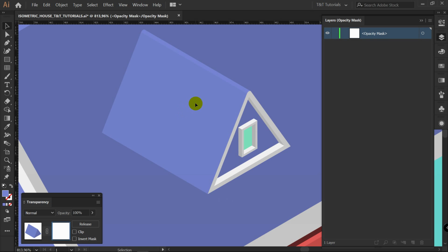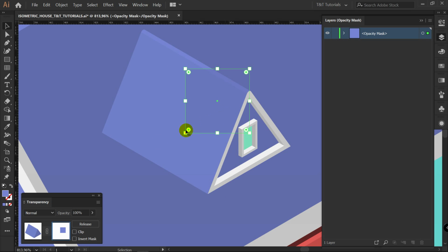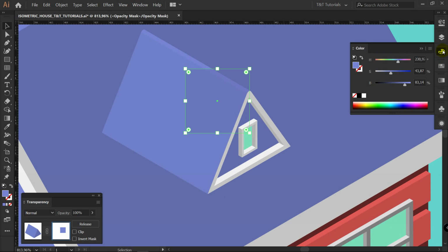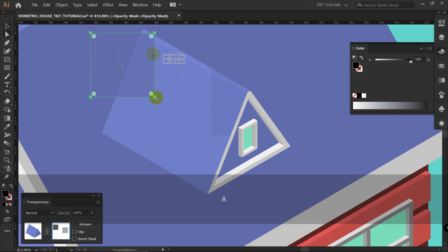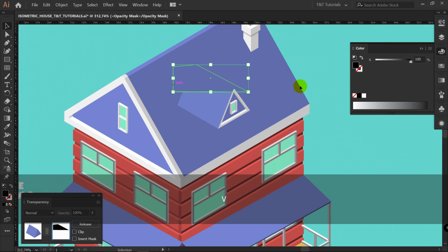The main thing that you need to know about a mask is that black color hides and white color reveals. And in a mask there are no colors. There's only black color, white color, and all grades of gray. So let's just create a rectangle. Right now it's hard to understand what is going on. It has some color, and for the mask this color is gray. Let's click here on color, grayscale, and you can see that the mask sees this color as some kind of gray. Let's make it black. And you can see that you can hide any parts of these objects, like so.